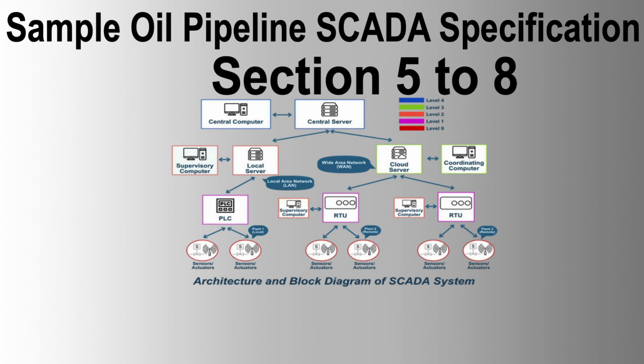5.10 I/O connections, provision for easy removal and replacement of I/O modules without powering down the RTU. 5.10.1 Removal of I/O modules, designed to allow for removal and replacement without interrupting RTU operation. 5.11 Status input requirements. Isolated from high electrical noise, filtered for contact bounce, and configured to handle pulse counting accumulators.